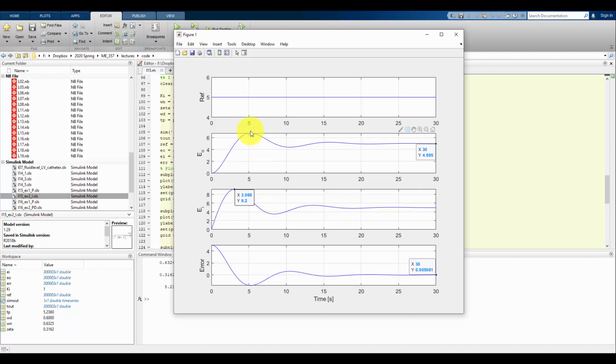And finally, we're seeing we do have an overshoot since it is an underdamped system here. So we do have a higher voltage at peak than what we want at steady state. So it goes up to 6.7 volts. But we can impact what that peak voltage is going to be, or what the overshoot is, by choosing different gains, because the max overshoot is determined by the damping ratio, and the damping ratio for this closed loop system is going to be determined by the gain we choose.